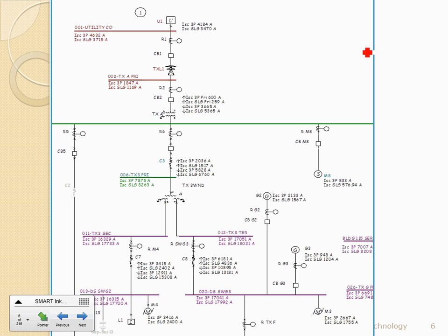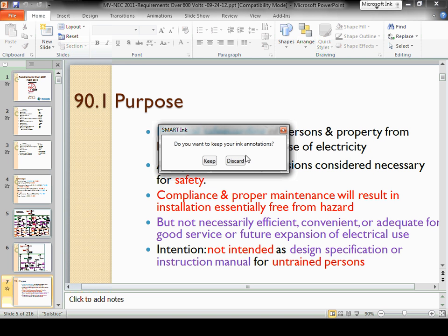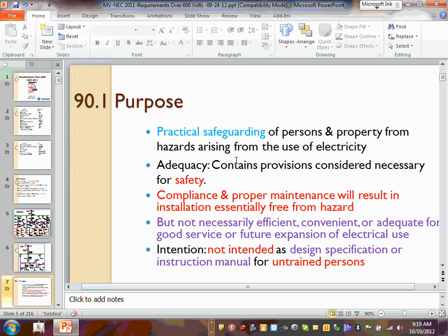But like I said, there are still engineers out there that put this together as their riser diagram and try to get the power distribution for a building across with this information. I have always thought that a riser is more contractor friendly for bidding purposes. You're absolutely right. From a bidding standpoint, really great. So this is a one-line diagram. When it comes to analysis, you are dealing with one-line diagrams. Every time you come to analysis, short circuit, coordination, harmonics, you name it, you're dealing with a one-line diagram.